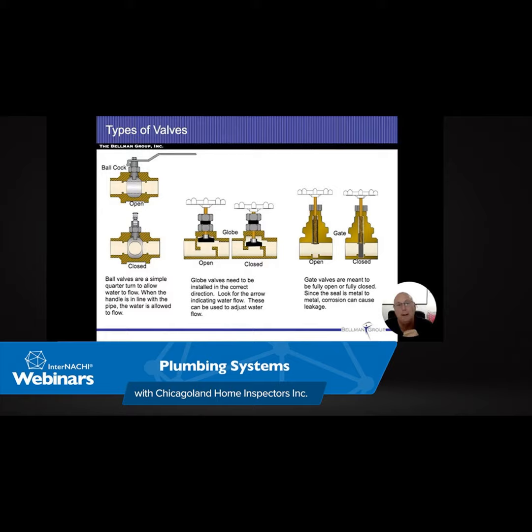Lead, I'm not aware of any lead that was ever hard temper. Lead is a softer material, and most of the water lines coming in that are bendable, that are silverish in color, are going to be lead. The telltale sign for a lead pipe is going to be that egg shape at the end.